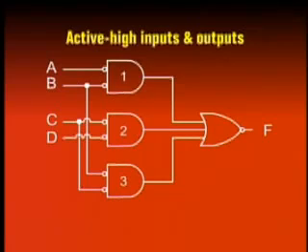By modifying the circuit to have active low inputs and outputs, the circuit sets the output F to active 0 to indicate detection of adjacent ones. Since the inputs are also represented by active low, therefore the input ABCD equals to 0, 0, 0, 0 actually represents 1, 1, 1, 1. Similarly, ABCD, active low input 0, 0, 0, 1 actually represents 1, 1, 1, 0.